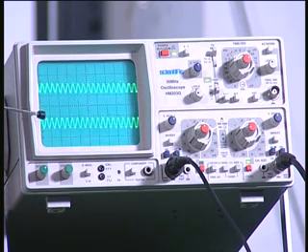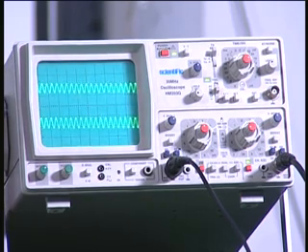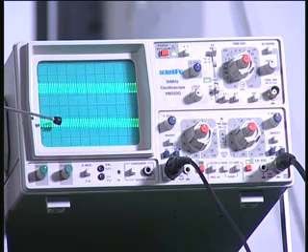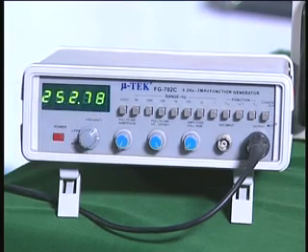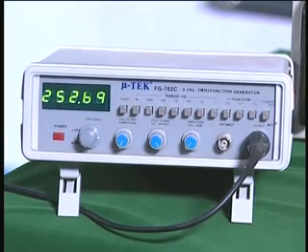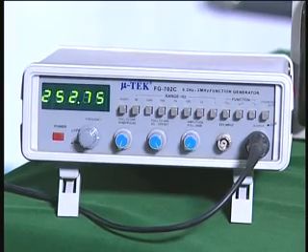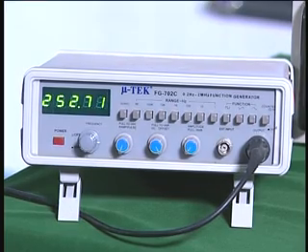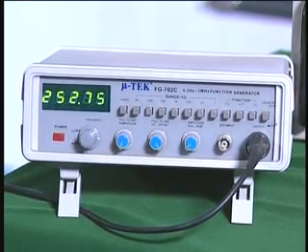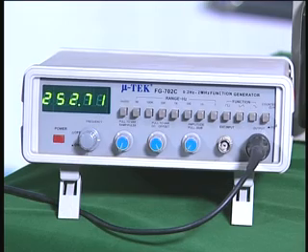Now I come back, now it is nearly 1 centimeter, 1 division on the screen. Now as I increase the frequency you find the amplitude starts decreasing. So this corresponds to very close to the cutoff, and this comes in the 100 kilohertz range, about 200 kilohertz or so. Previously, when I used a gain of 1, it was happening till 700, 800 k, you had no fall in the gain, but now you do get a fall at a much lower frequency, and therefore the gain bandwidth product means that when you increase the gain the bandwidth decreases.